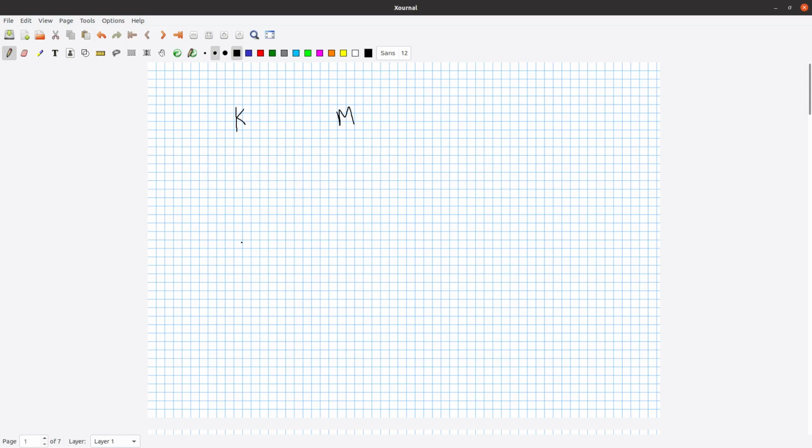Now, whenever you create a node, so here this black dot represents a node, each node has 6 degrees of freedom. You have 3 degrees of freedom for translation, and then you have 3 additional degrees of freedom for rotations. So you would have something like that.